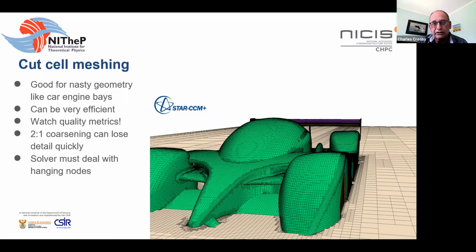There's a lot to that method numerically, and it's quite difficult to get it to do it well. But this has become one of the most popular methods of dealing with real life geometry. But this immediately breaks down that idea, unfortunately, of the grid lines following both the contours and the streamlines.